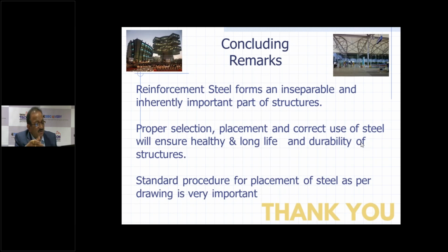And if still some corrosion happens, the age old practice is to put cement water slurry on the steel bars and then use it. But there are also some corrosion resistant paints available in the market these days, which are very frequently used for high durability.